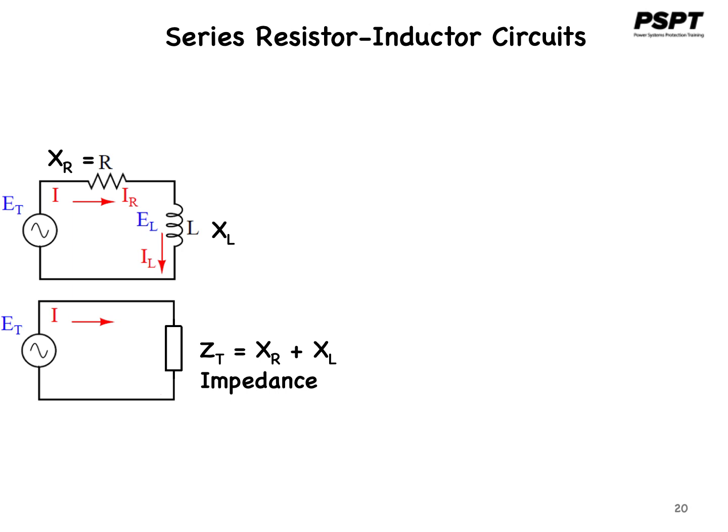If we take a closer look at this series resistor inductor circuit, we know that the current through each element of a series circuit is the same because that's the characteristic of a series circuit. The current in each element of the circuit is equal to I. In other words, the current through the resistor is equal to the current through the inductor is equal to the supply current. And those currents are vectors or phasors.